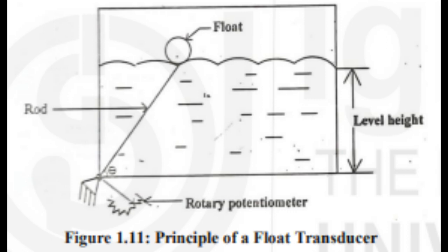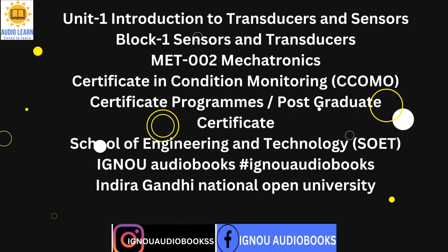The voltage output from the detector circuit is a sawtooth. This is fed into a Schmitt trigger, which is a digital device that converts the sawtooth pattern into a square wave. The square wave, with amplitude of 5 volts, is digital data in a form that is readable by a digital controller. It is typical for the detector circuit to output a high signal when light is blocked and low signal when a slot is encountered.